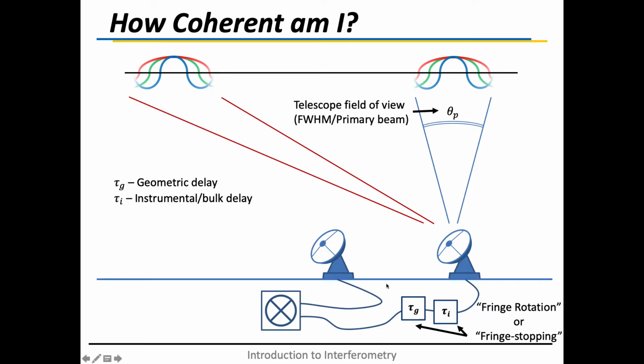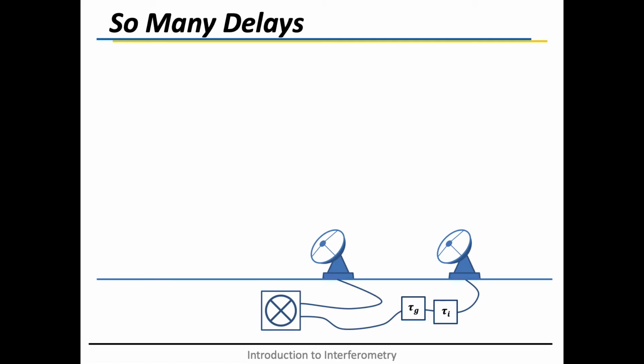So rather than measuring just the output of the mixer, where the signal has only one delay in it, you can introduce a box that outputs signals with multiple different delays and measure the output voltage from different correlators or mixers for each of these different mixing products.